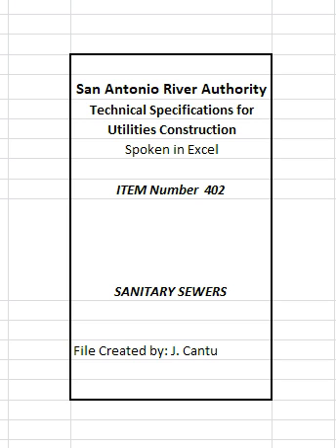1. Water line/new sewer line separation. When new sanitary sewers are installed, they shall be installed no closer to water lines than 9 feet in all directions. Sewers that parallel water lines must be installed in separate trenches. Where the 9-foot separation distance cannot be achieved, the following guidelines will apply.